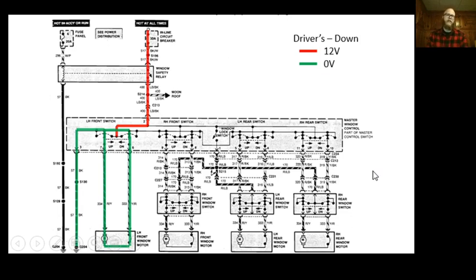So just isolating the driver's circuit all by itself, this one's obviously the simplest out of the four. When the vehicle is sitting there without a key in the ignition, no one's around, there is no power that makes it past this relay. It's not until we actually turn the key on, see this is hot all the time, but it deadheads at that switch. You turn the key on to accessory, right? So 2 clicks so that we can actually roll windows up and down or start the vehicle up. Then it sends current through the coil down to ground over here,